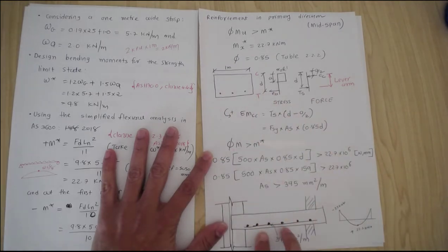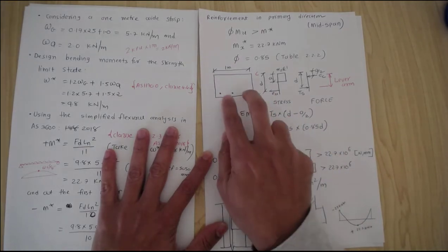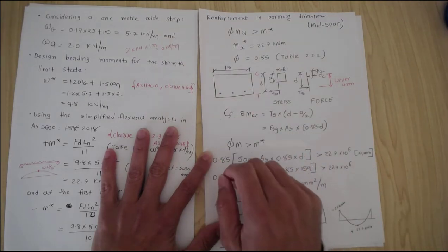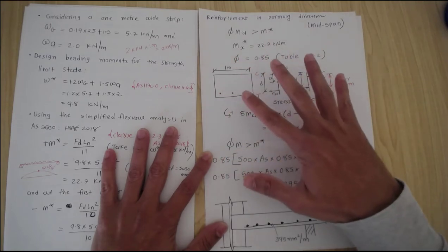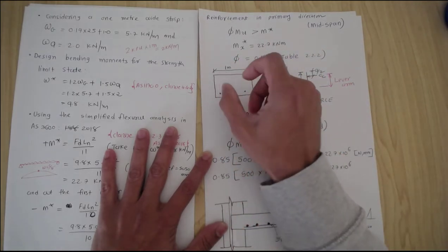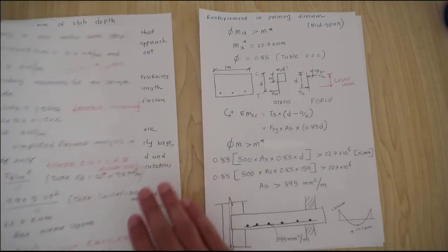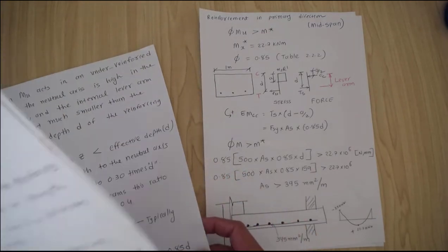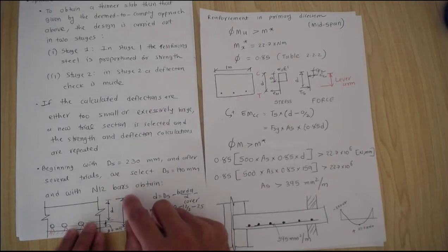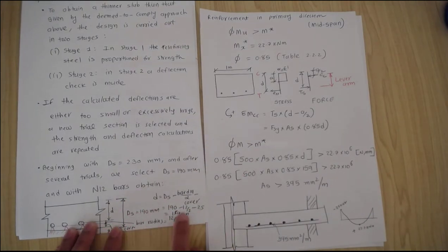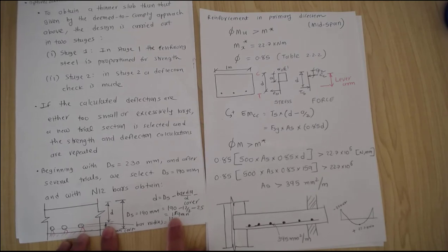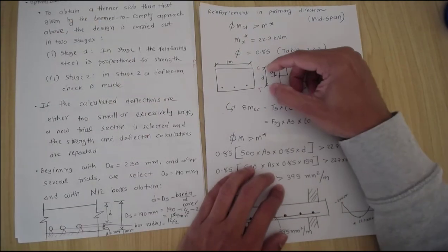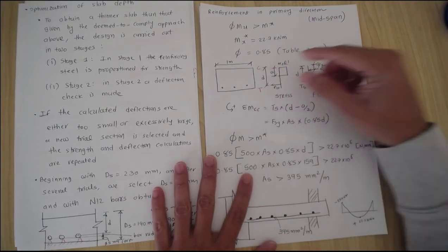Now we assume a 1 meter wide strip, where we're going to find the reinforcement, and then based on that, the spacing that we're going to provide per 1 meter. This is exactly the same scenario as a beam. So the beam is 1 meter wide, and the depth of the slab that we calculated, DS, was 190 millimeters, and based on the cover and reinforcement, we found 159 millimeter was the small d. So here we have the same concept that we used in the beam.